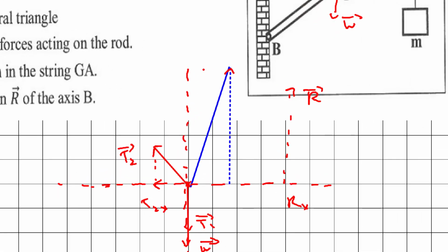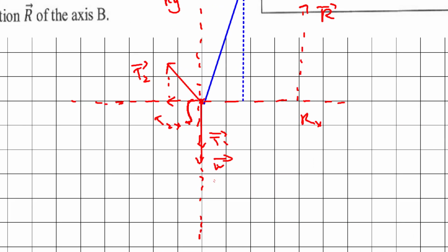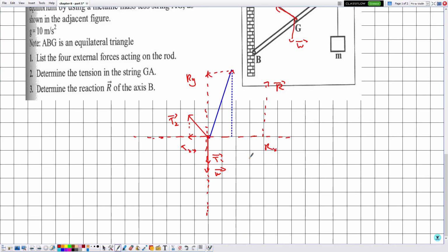Now what about the y component? So this projection, which is Ry, must completely cancel the sum of these two. So this is 2 and 2.5, so they add up to 4.5. So they must completely cancel these 4.5 that I have represented here. But not worrying about all of these, this is just a discussion about if our answer will be correct or not, how one can check the answer.